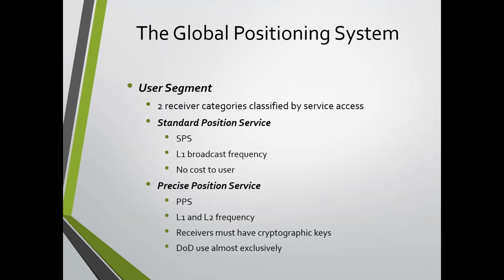And when you buy receivers, the more frequencies that you can get through that receiver, the better you get. But most receivers are dual frequency, which means they pick up L1, L2. And now, of course, the newer ones also probably have L1, L2, and L5. If you have the very original first year group, or the first probably 10 years or so, most of your receivers were single frequency. So they were really limited in what they could do.